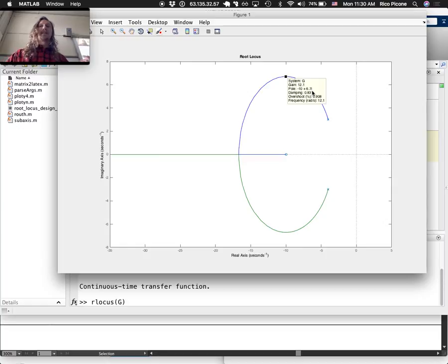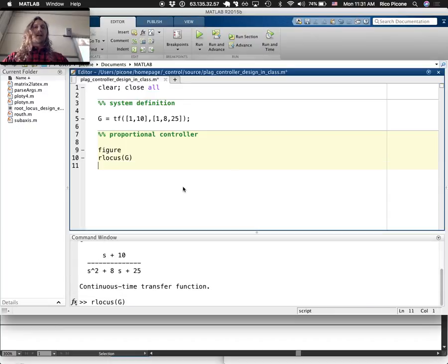So that is our gain that we would associate with the transient response that we desire. So let's just go ahead and put, let's call it our K1, and it equals 12.1. When I did this last night, I got 12. So, you know, there's a slight variation every time you do it. Okay, 12.1 is our gain. So we actually have designed a proportional controller. We're like already done with the proportional controller design.